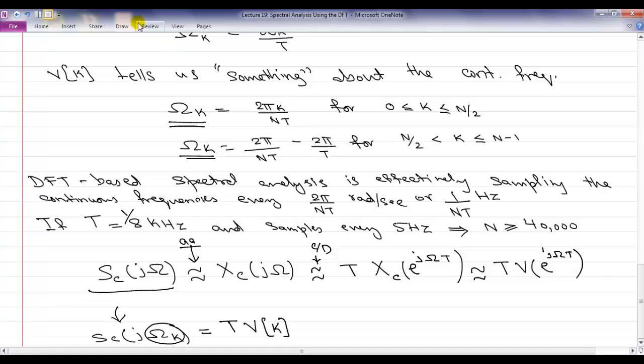The other half corresponds to understanding that these approximations are not true, that this equality is actually a big approximation, okay? Even though the anti-aliasing filter and the continuous to discrete conversion can be ideal, this approximation, which is due to windowing, has non-negligible effects.